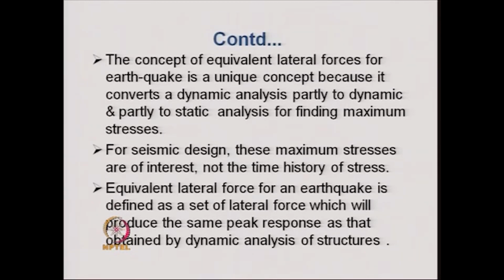It is partly dynamic and partly static because in the first part of the analysis one has to find out the mode shapes and frequencies of the structure, and in finding them one has to perform a dynamic analysis of the system, or rather you can say one has to solve an eigenvalue problem.